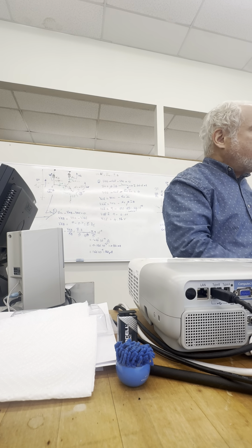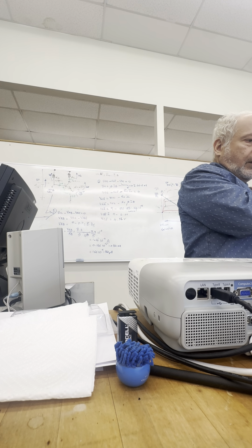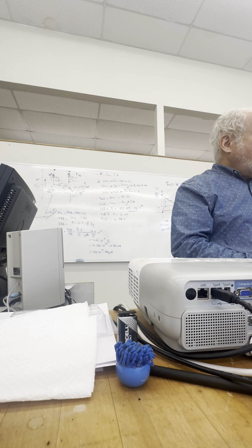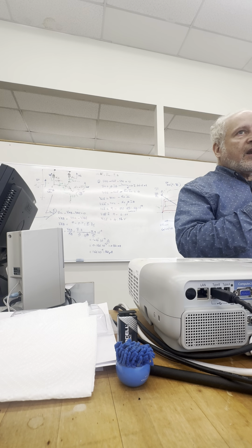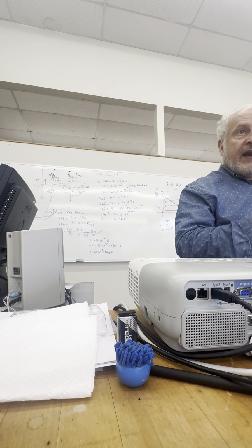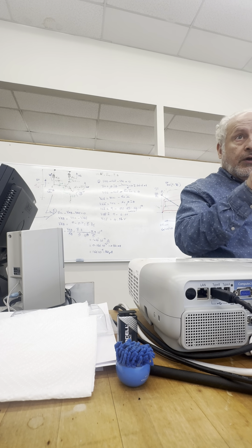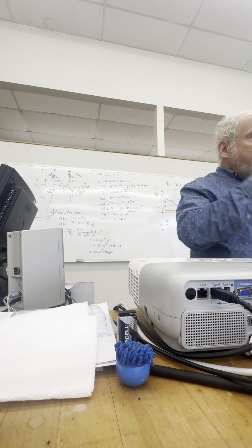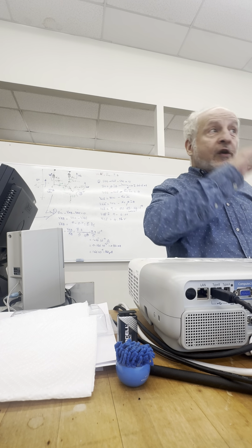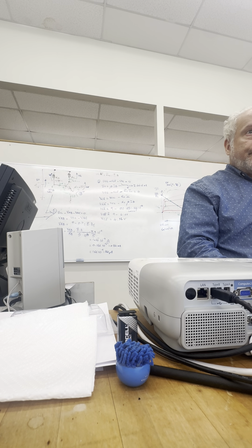Now, if the manufacturer of that motor says you cannot have a maximum current of more than 1 amp, well, great. Right? So I know my IC of saturation cannot be at 1 amp. Maybe I'll bring it down by 80%. You with me so far? Down to 80% of 1 amp. That's an operational zone. You look at the specs of the motor, and you say, where would it be happy to operate? Where it's not overheating, where it's okay, given any temperature, what temperatures you're working on. You with me so far?